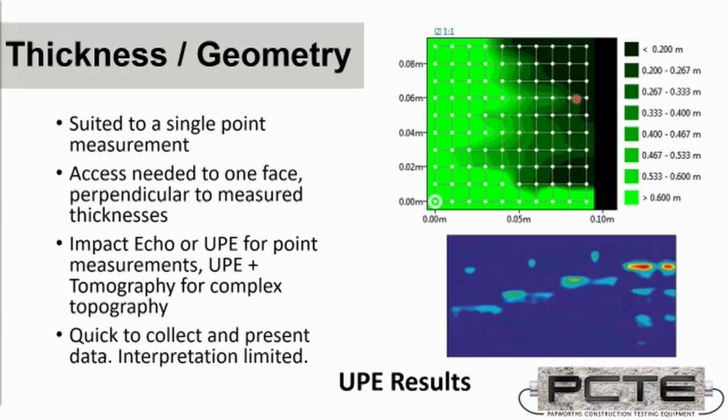So in this region, it's actually finding defects, and we've relied upon these locations of thickness, which vanish when we have air above them, voiding above them. So it's always good with ultrasonic pulse echo techniques or impact echo techniques to have them respond to thickness, because if you lose your thickness measurement, that can be a strong indicator there's voiding or something else in the way.